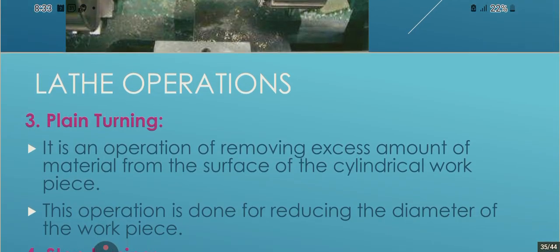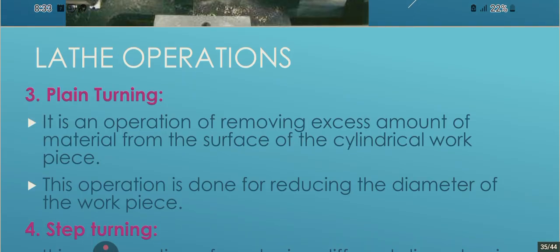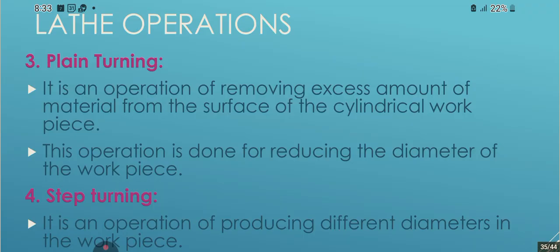Lathe operations. Plane turning is an operation of removing excess amount of material from the surface of the cylindrical workpiece. This operation is done for reducing the diameter of the workpiece.